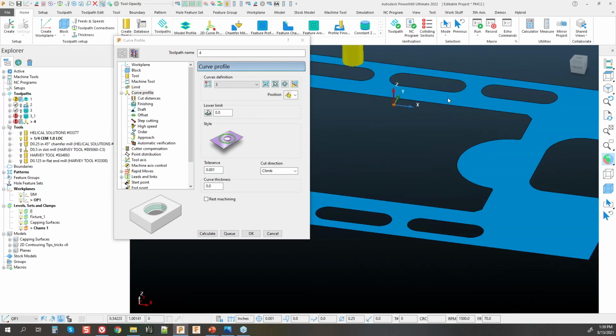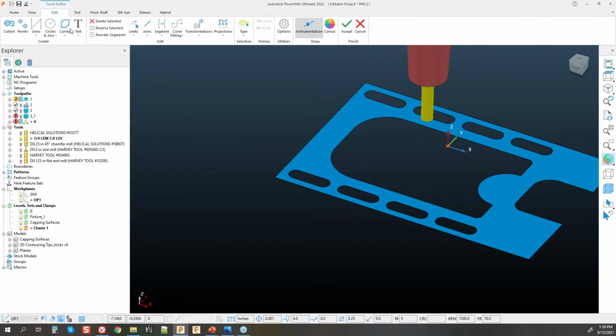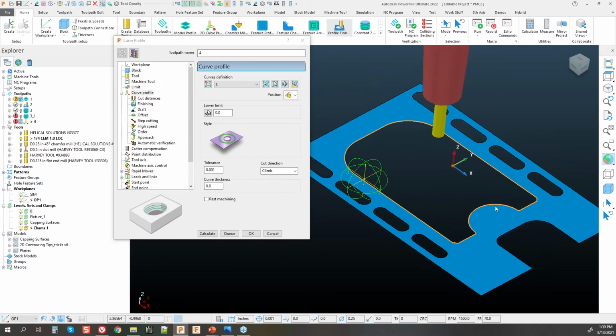Once I have that blanked out, except for what I want to actually select, I can use the composite curve tool and select that edge. It's going to snap itself chained all the way around. It just has one selection to find. There is nothing else in the way. You're going to have an easier time selecting your geometry with the composite curve tool this way, and you'll get nice clean chains out of that pattern.